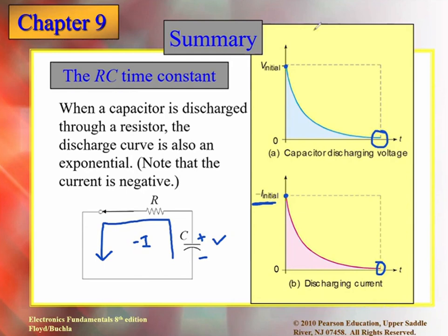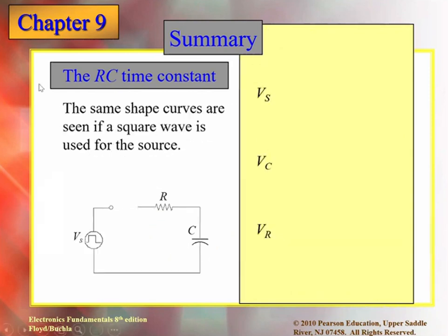Okay, so this is the basic understanding of charging and discharging of the capacitor. Based on that, you have a lab experiment also, so you must know this concept for the lab also, right? Now see this one. Do you remember the pulse waveforms which I taught you in the previous chapter? Pulse waveform, correct? This is the time period, periodic pulses, right? So if I say its maximum value is 5 volt, minimum value is 0. So see now, interesting thing. At this time it is having high voltage, at this time it is 0. Correct? 5, 0.